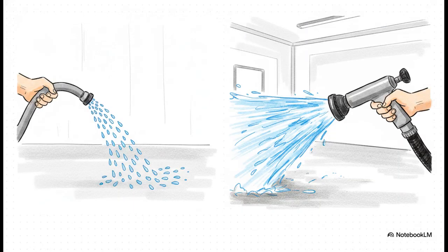And then we have sanitization and hosing down areas. Think commercial kitchens, dairies, or car wash bays. Here, the safety rules shift based on sheer mechanical force. If the area uses low or medium pressure hosing, the electrical equipment has to be upgraded to an IPX5 rating. But if they're blasting those walls with high pressure hoses, the equipment must achieve a rigorous IPX6 rating. The standard literally adapts directly to the physical velocity of the water being thrown around.